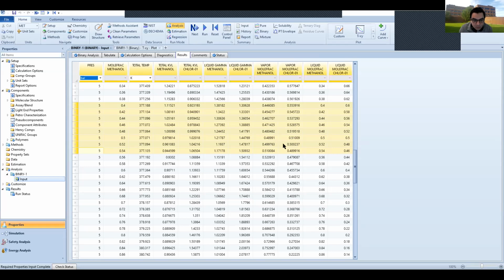The cross seems to be happening somewhere here, right? No, around 0.52 mole fraction of methanol, right? So this seems to be where my azeotrope occurs. And again, I'm not looking at these liquid values because this is what I'm plotting, this is what I'm changing basically, and this corresponds to this. These two are the same value. But I'm looking at the vapor mole fraction, and the azeotrope happens when they intersect.